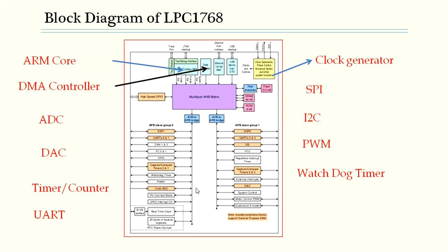So is the functionality of the Watchdog timer in LPC1768. Whenever there is an error, this Watchdog timer resets. When enabled, the Watchdog timer will generate a system reset if the user program fails to feed or reload the Watchdog within a predefined amount of time.